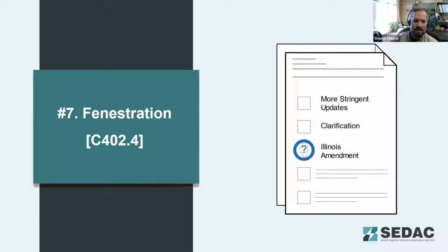The energy code does not state a limit on the air conditioning sizing. It does have that equipment watt per density listed in there, and so you would have to properly size the air conditioning equipment for the loads in that space. But outside of that, the energy code doesn't have specific requirements to qualify as an equipment building for the specific envelope exceptions. And when you get into the HVAC section of the code that we'll talk about in our next webinar, the requirements for proper equipment sizing and things like that would still apply for air conditioning.